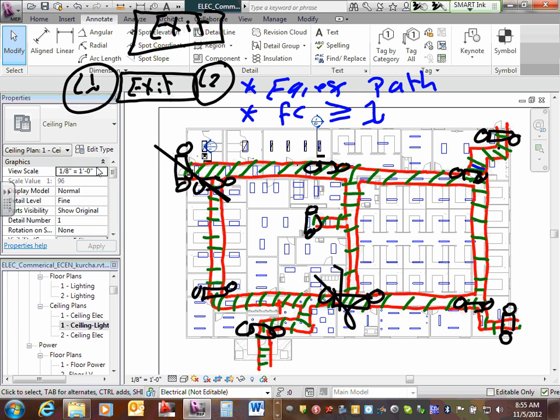So that's typically, most likely, what you're going to do. You want that one, just emergency lighting, without the exit sign? Yeah, you could. In this one, there's a door, isn't it? No, there's no door. So this one could be an emergency light only. It looks like this. So that will be E only, emergency only. Any comments, any questions? So standing right here, you can see an exit here, and an exit here, and an exit here, plus light to lead you through it.